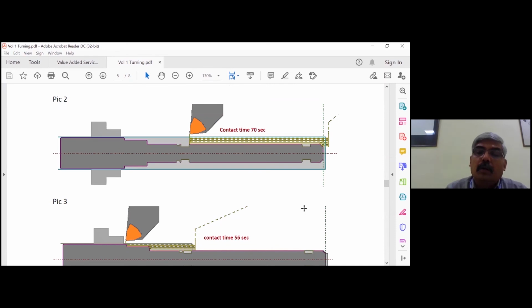The next case we took, same length of 220 mm, we divided into 4 segments. That means first 55 mm, second 55 mm, third 55 mm, last step again. The advantage is I want to keep the diameter as it is. See now, the total rapid time may be around 5-6 seconds, the retraction and going back and other things. But that continuous running had a fixed limit. That means I had to use only 0.25 feed rate, 0.3 means 0.3, and again chip winding.